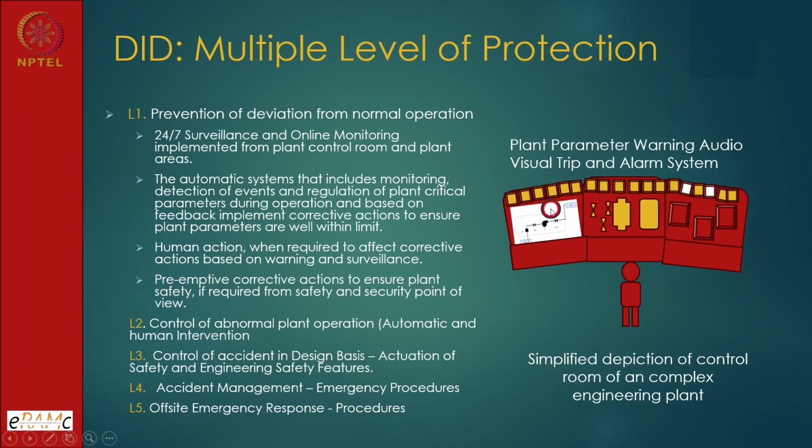The second part is there are hardware matrices, which are shown here, and the operator will get the status of the plant after seeing this, like here pump, suction valve, discharge valve, tank, and some recorders will be there. So we will know the status of the plant by trip and alarm, which is visual, and they have visual and audio indication.